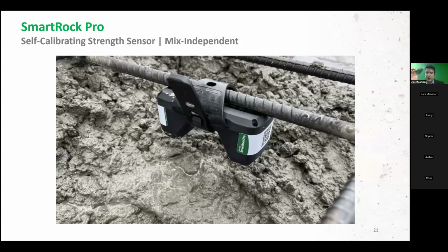Okay, please. Basically, this sensor follows the ASTM C1074. It only replaces your field specimens. It doesn't replace your lab specimens, right? Only the ones for the early ages. This sensor is a patent pending technology, okay? It is not approved by any standard so far, so it can't replace anything, right?